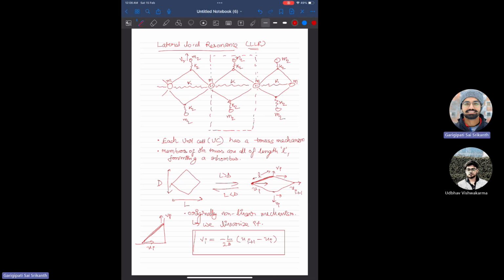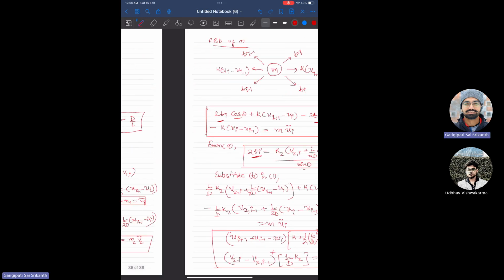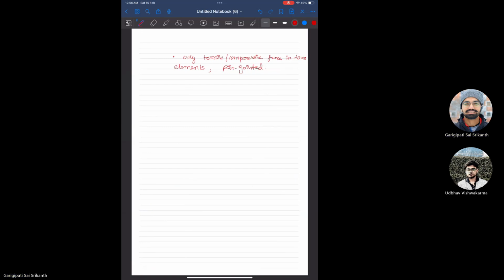Or if this beam was not straight, if it was curved in some way, then the point of action changes. So then you'd again see some sort of shear or bending moment. Because it is straight and it's pin jointed, it's like making it really, really easy. Then we assume that they are massless. I'm just listing out some of the assumptions that make this impractical and why we slowly go towards inertial amplification. So this is right, this is massless.